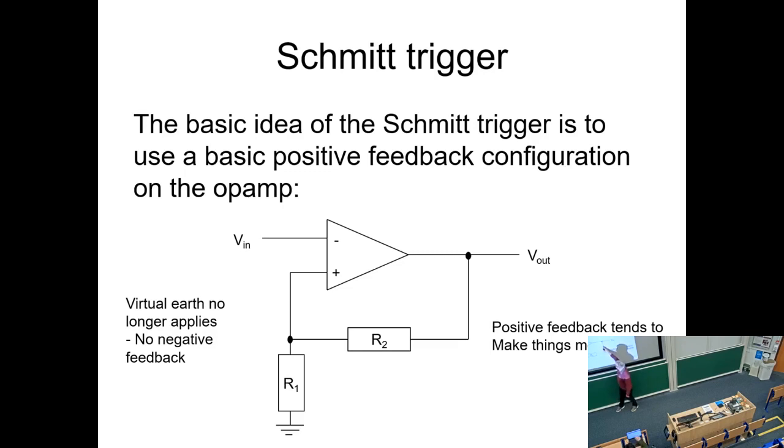What that actually means is that this output will head towards, I don't know, minus 10 volts, because that's the other supply rail. This voltage will become minus 5 volts, because it's half the output voltage. Now the voltage being compared on the reference pin is minus 5 volts. So that's suddenly moved from plus 5 to minus 5, which is probably a very long way away from this one, because this one just triggered at plus 5. So this one's around plus 5, this one's now gone to minus 5, and it's waiting for Vin to move down to the next level to trigger it. So it's sort of a variable reference that this thing has created.